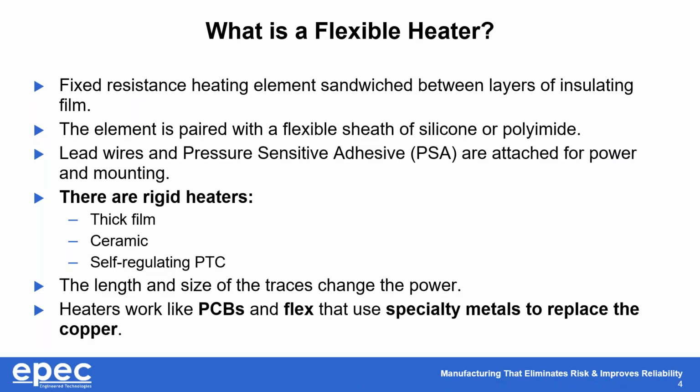What we'll cover today will go into detail about how the length and the size of the traces within the heater provide all of the power and the characteristics for the heater, and we'll go through details on how to properly size and develop those traces for your specific application.